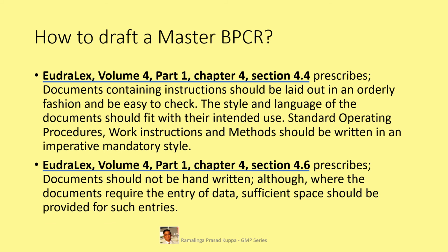Eudralex, Volume 4, Part 1, Chapter 4, Section 4.4 prescribes documents should not be handwritten, although where the documents require the entry of data, sufficient space should be provided for such entries. So it is also clear that a BPR or BPCR cannot be written in a handwritten way. It should be in a printed way, and only there should be a provision to enter the data, and there should be sufficient space to record the data.